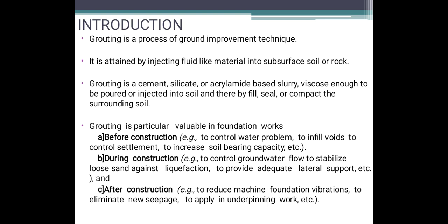Grouting we can apply in almost all phases of the construction work, before construction, during construction and after construction, where it plays a very important role. Before construction, for example, to control water problems, to infill voids, to control settlement, to increase soil bearing capacity, etc. During the construction phase, to control groundwater flow, to stabilize loose sand against liquefaction, to provide adequate lateral